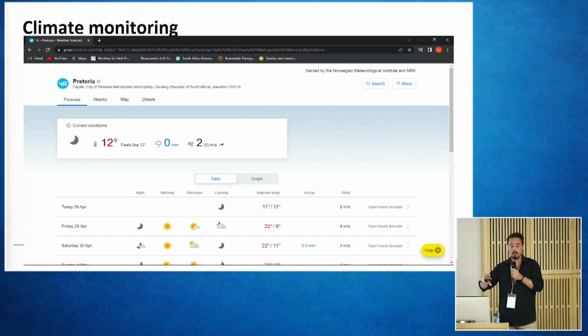With all of these sites, and with getting data from the Weather Bureau, it's important to realize that it's not going to be very specific to your site because they use the closest weather station available. So if you really want very accurate data, it's more important to use a weather station. You can even use just iButtons if you're just interested in temperature and humidity. But if you're interested in really accurate data, we would suggest going for a weather station and monitoring the weather in that way.